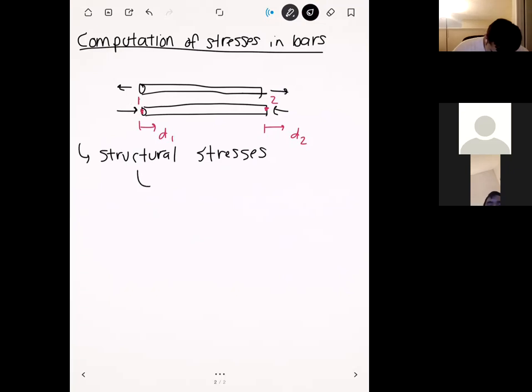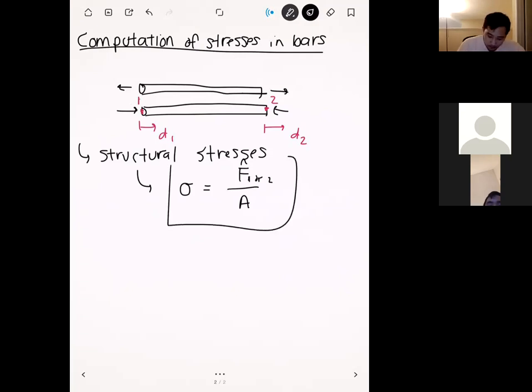The way we can define stresses, at least in a bar element, is to simply take the force that's being applied at a node and divide it by the cross-sectional area. To put this in terms of quantities we knew before, I'll give this force a hat, which tells us the force is down the length of the member, in other words, in the local coordinate system for that element. You can compute the force at either one end of the bar or the other end.